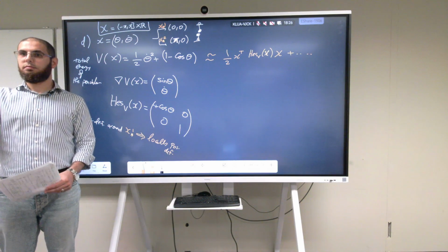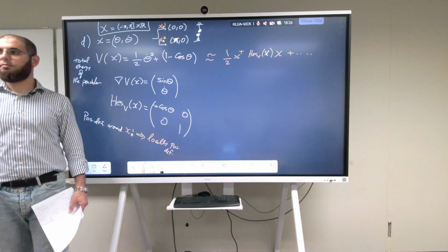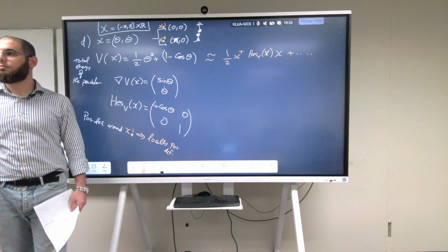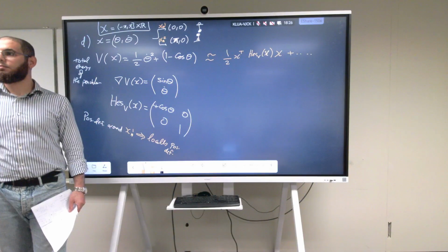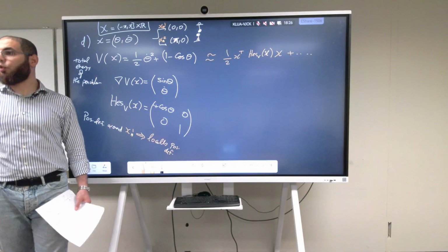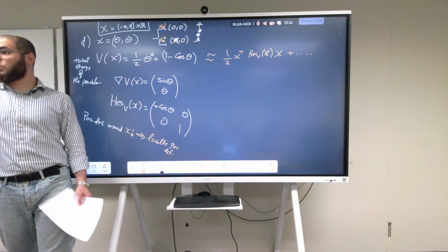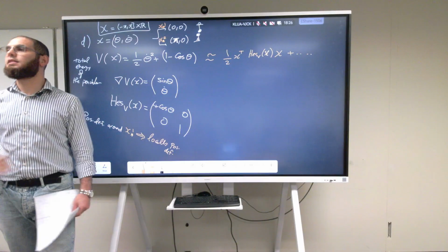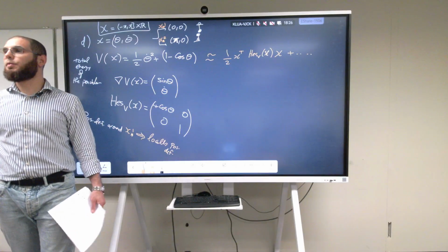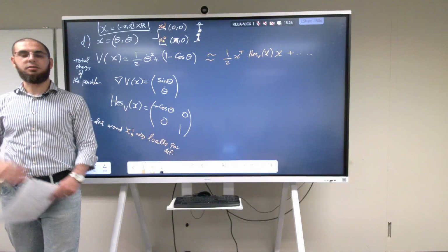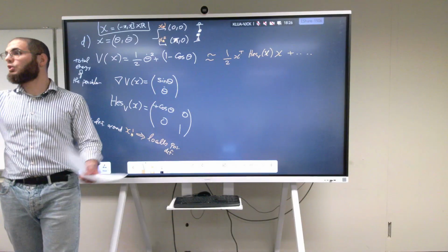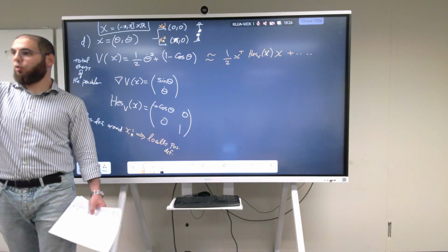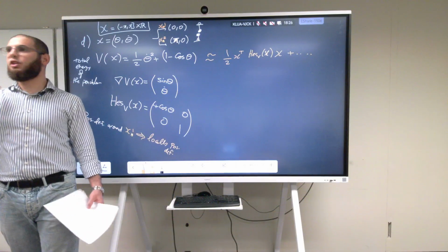A follow-up question would be why didn't we use a similar function to what we used before, like half theta squared plus half theta dot squared, for example? So the quadratic form, you mean? Yeah, exactly. Use it, and you'll find I can easily say it's 99% of how people do control and use Lyapunov analysis. Just start with the quadratic function. If it works, it works. Wouldn't it always be positive definite? The function would always be positive definite, absolutely. So you don't even need to check for it.